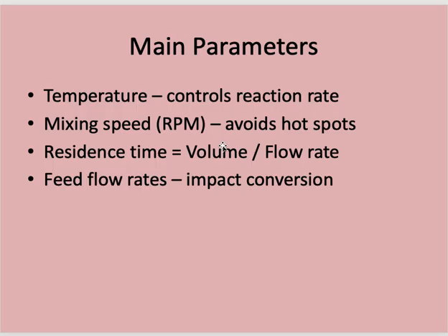What is the main parameter related to this type of reactor? The main parameter related to this type of reactor is temperature. We need to control the temperature. As we mentioned before, in the polymerization reactor, the temperature may be controlled by a coil controlling the body of the reactor, and the temperature also can be fixed by making a reflux by evaporative cooling. You can take the vapors from the top of the reactor and make cooling and return back in the liquid phase to the reactor. So the main parameter to control through the continuous stirred tank reactor is temperature, one of the most important,